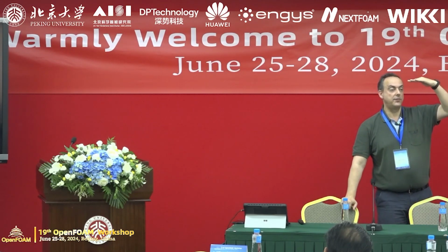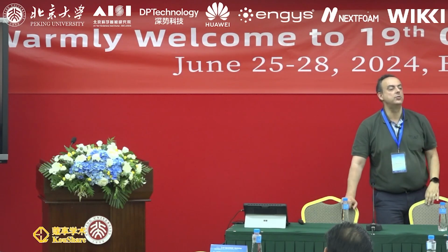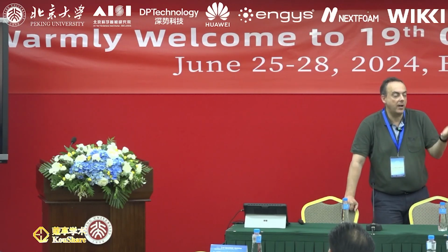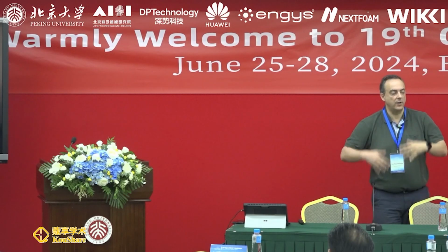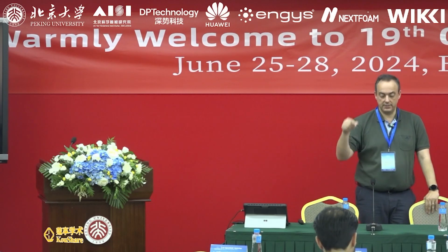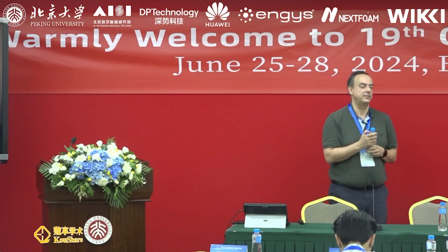So one of the details to optimize is the thickness distribution along the parison, and for instance, the amount of material you have in the container as well. Try to minimize it, because in many cases you want to assure permeability. So there is a minimum thickness you need to assure in all the package. And where this material came from is not easily identified experimentally.